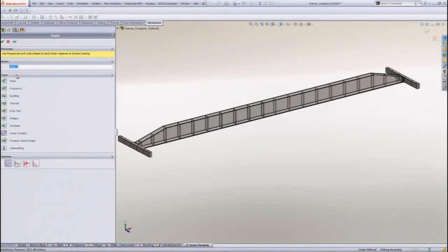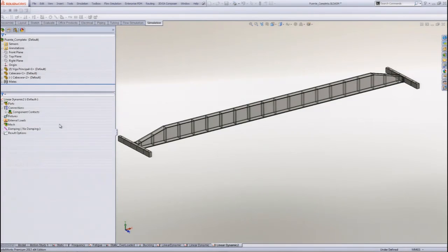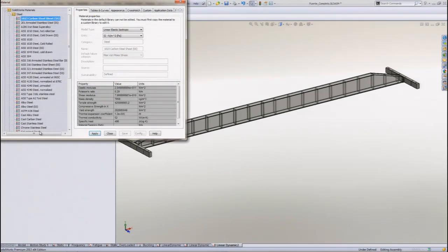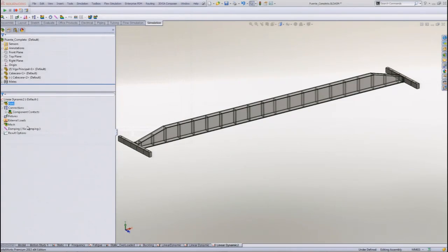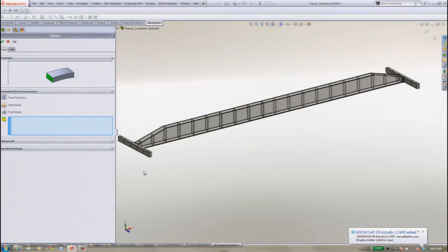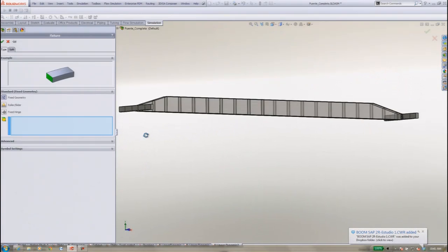In this case, we are simulating a load. We are simulating a kind of impact, but it is not an impact. It is simulating that we are lifting a 6-ton load with very high speed, right? So we get from 0 to the full 6-ton load in less than 0.1 second. And there we have a constant load. What we want to see is the oscillation of the bridge.